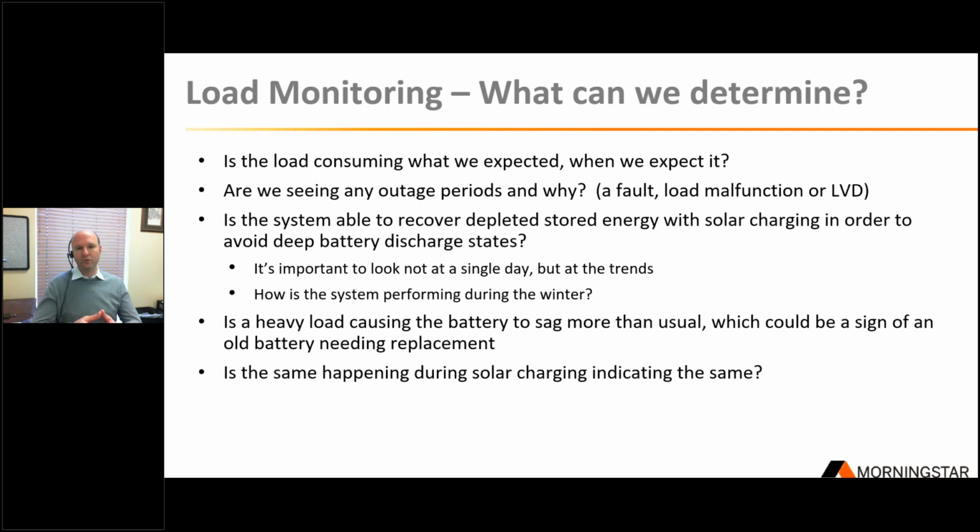We had some systems where our controllers actually monitor fault and alarm flags that are logged in the controller's data logging file. So if we see a strange short circuit that's occurring or a high voltage disconnect that's being caused by another device in the system, it's not anything we have control over. There's a nuisance being created because of some products that aren't compatible with each other. You can see that in the data log file.